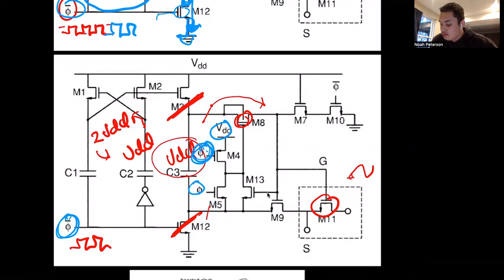When C is low, this PMOS is turned on, which allows a charge to flow through that transistor, going up here, being applied to the gate of that PMOS transistor, which then in turn isolates this part of the circuit, depending on whether this PMOS is on or off, to where only VDD can be charged up.